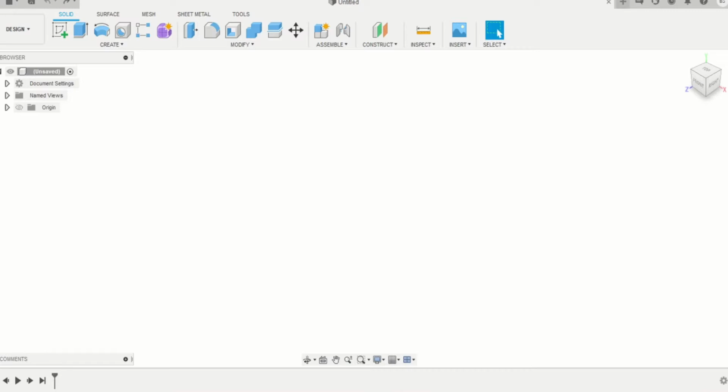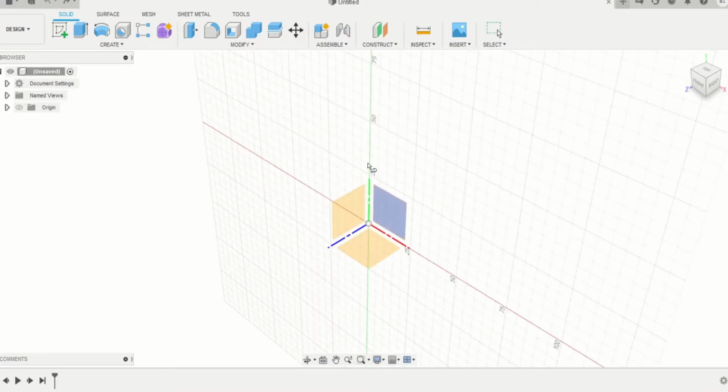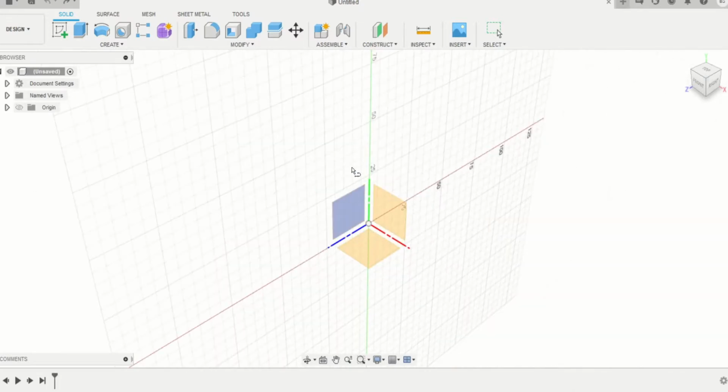Okay, so in order to get started, first of course, open your project or just open Fusion 360, you will get a basic project opened. And in order to create a sketch, you can either click the Create a Sketch button or just press L. Most of the time I will use L because it kind of reminds me from the function of line, which you can use to just create basic lines. As you can see, now the origin appears.